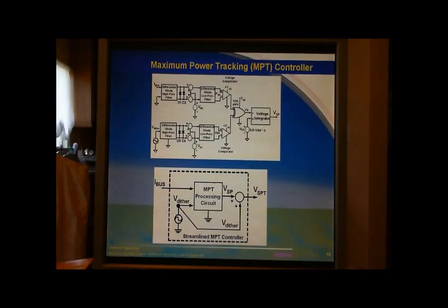These two AC signals convert to discrete voltage through their voltage comparators. As a result, these two discrete voltages appear at the input of the exclusive OR gate, which produces the processing logic at its output Vx.